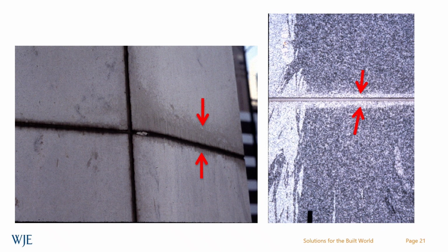A key ingredient in many silicones are plasticizers. You see 2 images here of plasticizer migration. In both instances, these are silicone-based sealants where the plasticizers or oils from the sealant themselves are absorbed into the stone and changed the visual characteristics of it as well as the hydrophobic characteristics of the stone in the area where the plasticizers have migrated into the masonry itself.